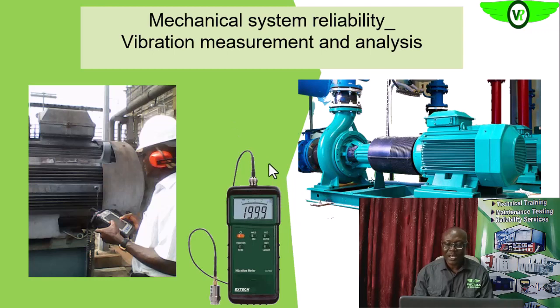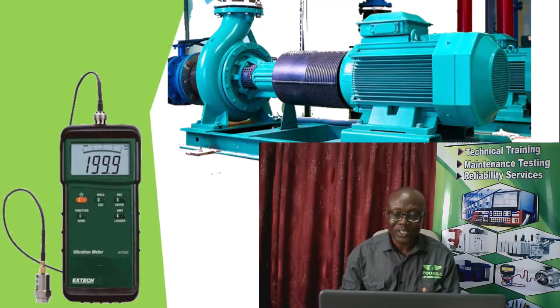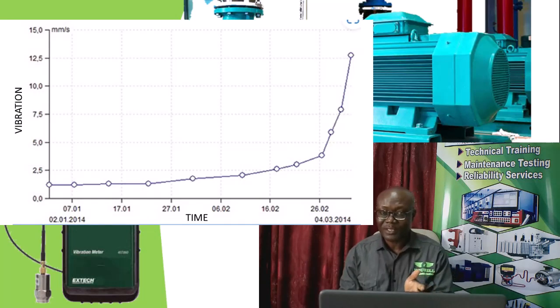Okay, so we have simple instruments like the handheld vibration meter that will be able to give us the overall vibration level of the electric motor and the pump. So if we take the vibration readings of the electric motor at the bearing housings, as we'll see later, in three positions or orientations around the housings, we'll be able to get the overall vibration reading with the vibration meter. So when we are trending this overall vibration reading, as the total vibration is changing, as it's increasing, we'll see it.